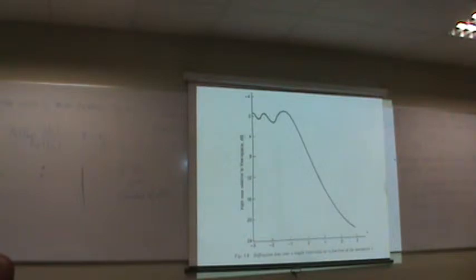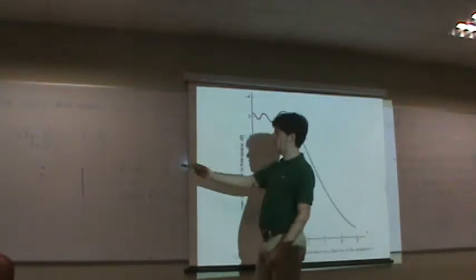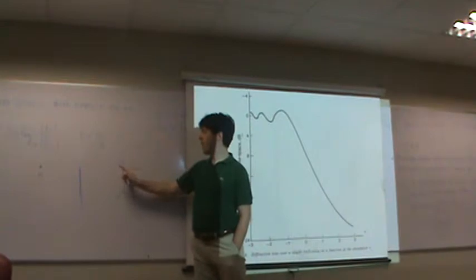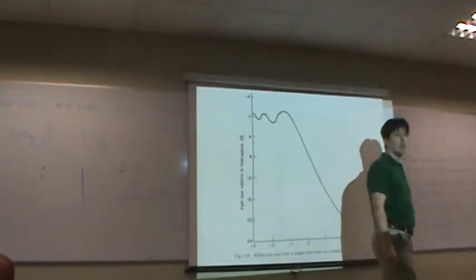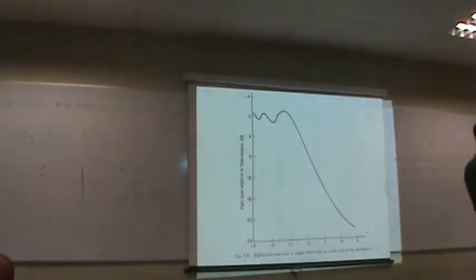Why? What is the physical reason? Why are we losing? Why is our signal half the signal that we would receive in free space, even if there is a line of sight between the two? If you think about diffraction, if you think about Huygens equivalent sources, you will find the physical reasons.